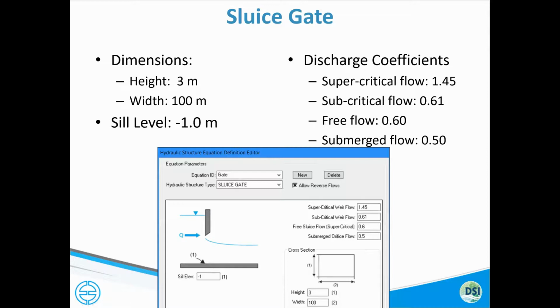So that's an uncontrolled sluice gate structure. The controlled sluice gate would then raise and lower this gate structure, as shown in this little diagram, based on however we have configured EFDC, either just a time-based value or actual water level values.